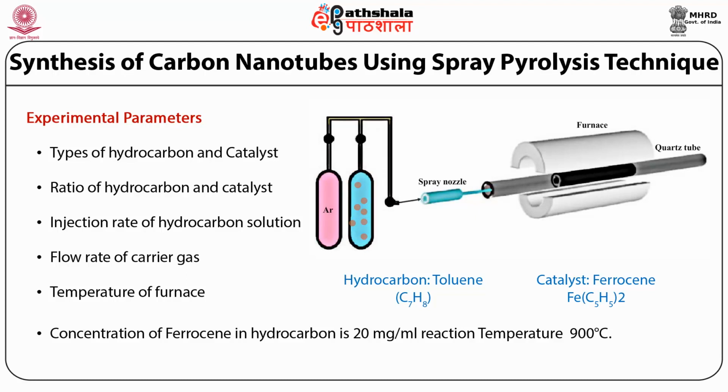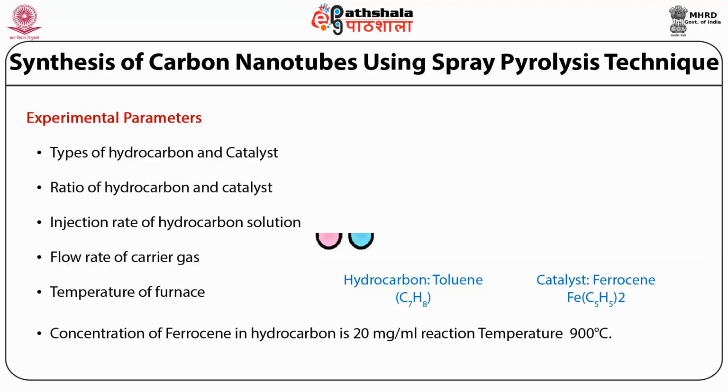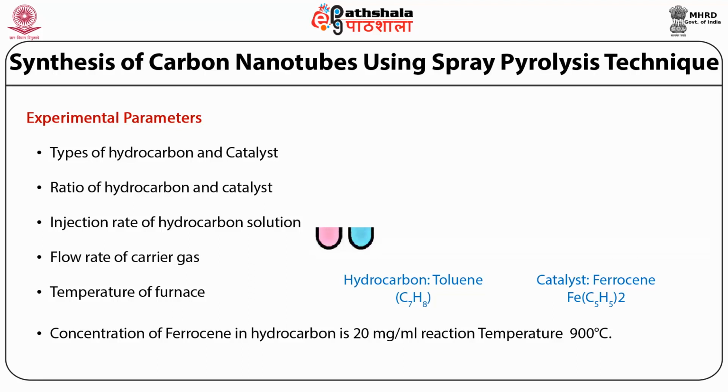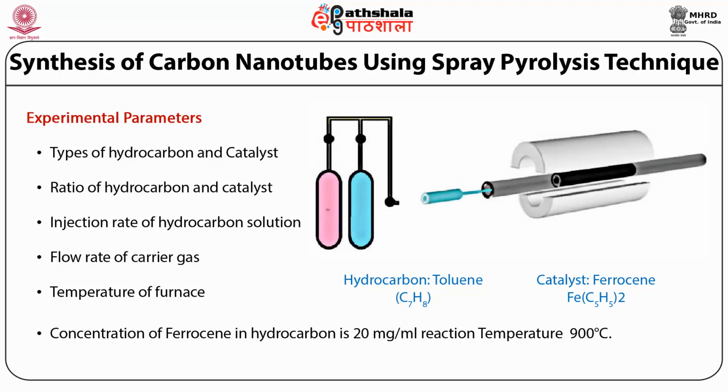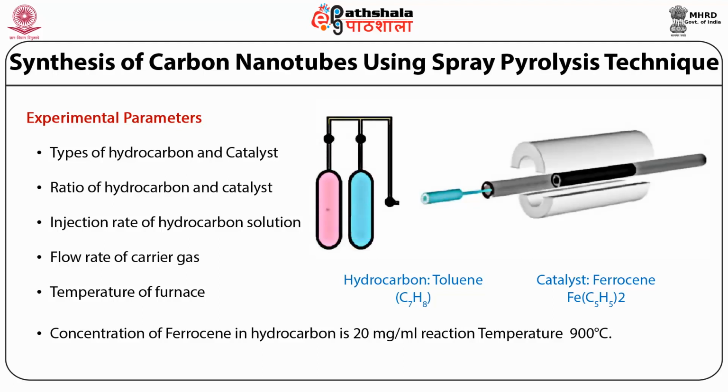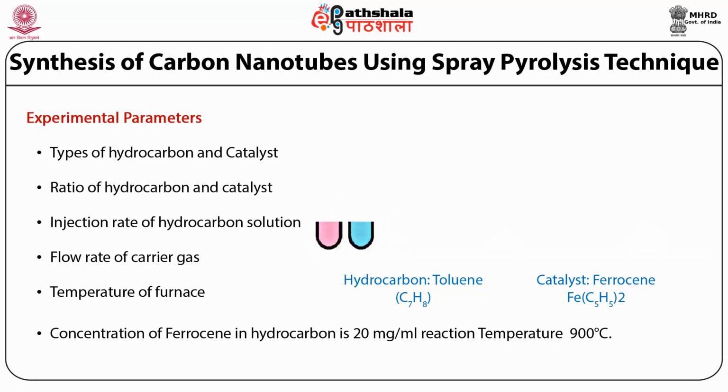Production of the macro architecture of aligned nanotube for use in filtration application. Here I want to discuss the synthesis setup, which is the spray pyrolysis setup. It consists of a nozzle attached to the ferrocene benzene solution supply, used for releasing the solution into a quartz tube mounted inside a temperature controlled cylindrical furnace.